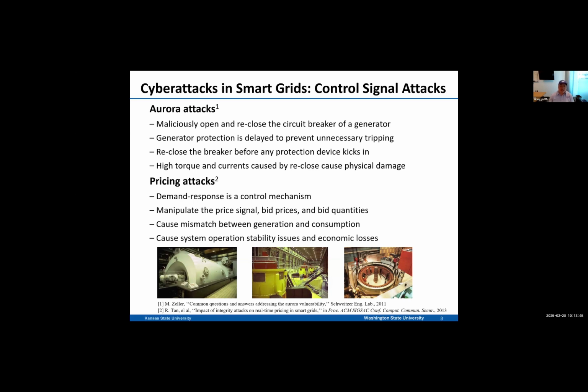The second attack is the PRESS attack. The PRESS attack works mostly through the demand response program. It can send in a scaled value of the true price and delay attacks on the price signal. The attack increases the mismatch between generated and consumer power. The attacker is capable of injecting false pricing information at any moment and repeating it over a long time duration. The power mismatch caused by the long-term attack can lead to power overgeneration, economic loss, and poor power quality.